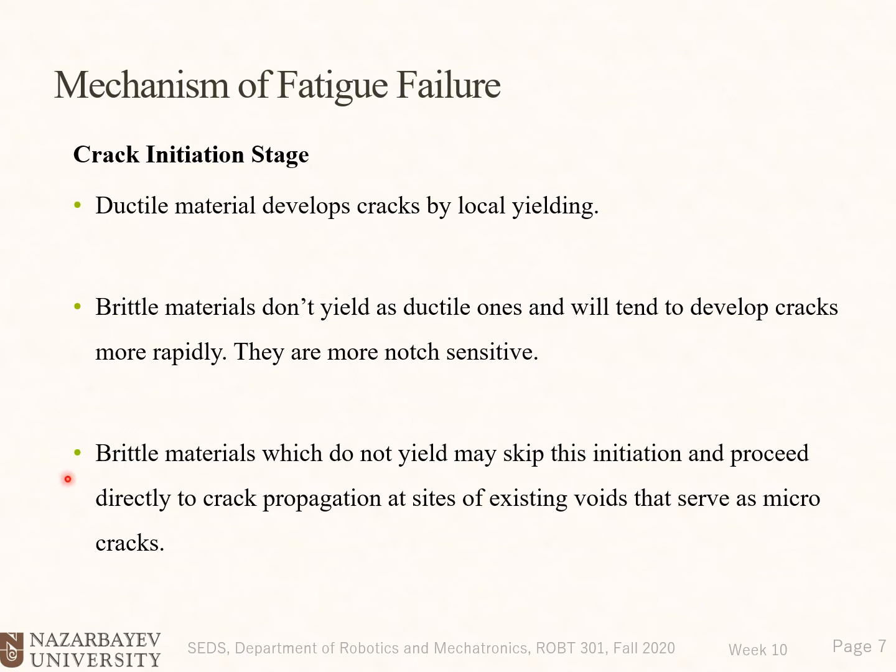Ductile materials which do not yield may skip this initiation and proceed directly to crack propagation at sites of existing voids that serve as microcracks.